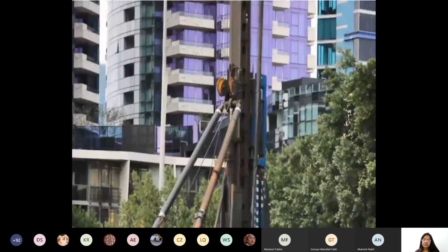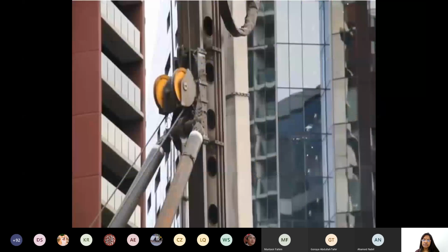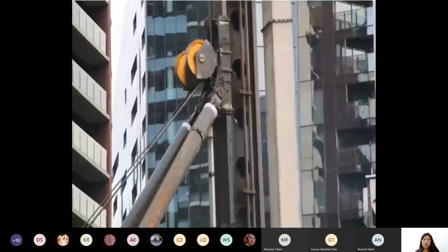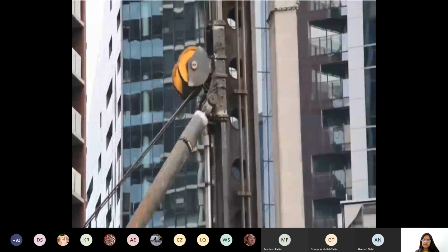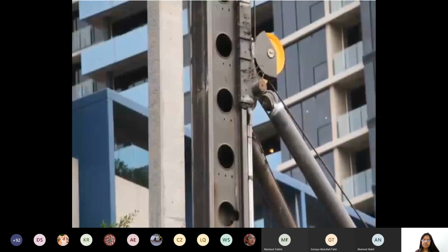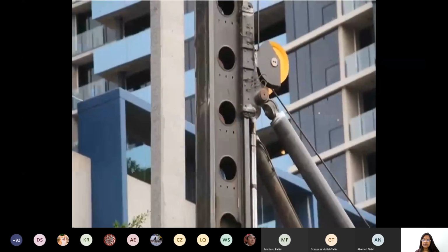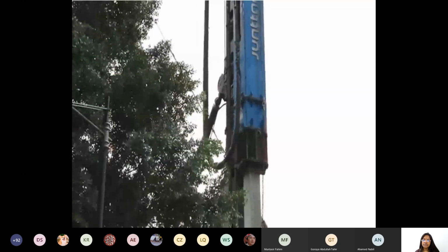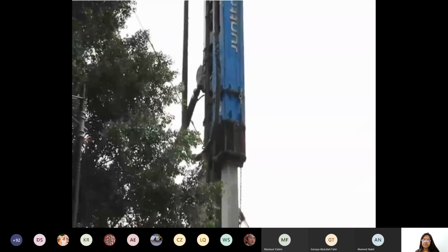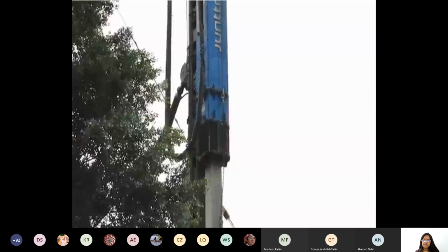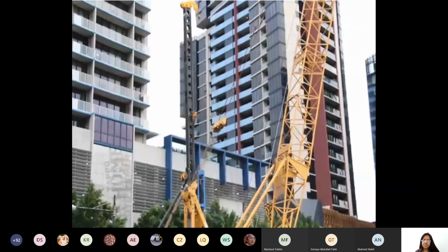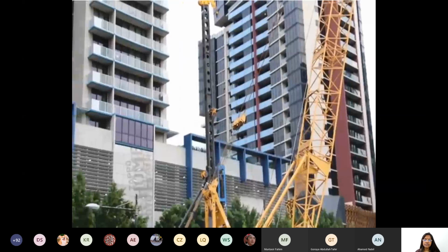Although it looks like a very simple process, the pile driving method requires very skilled operators and assistants due to numerous variations that need to be considered. A few examples of the factors that need to be considered by the operator when driving a concrete pile into the ground: the number of blows per minute, the drop height, the energy applied, the angle of the pile, the composition of the soil, layer by layer.